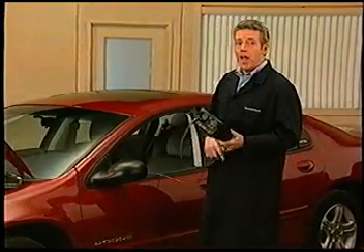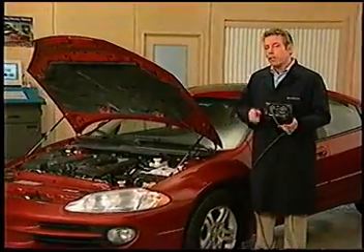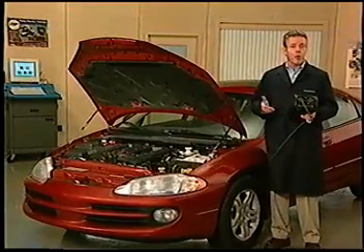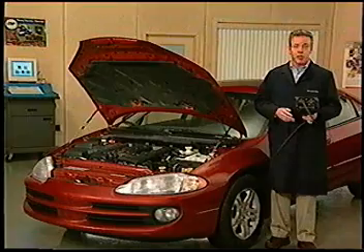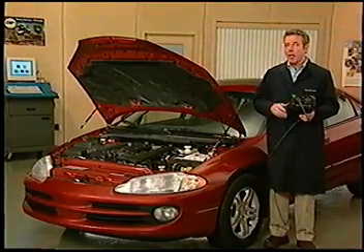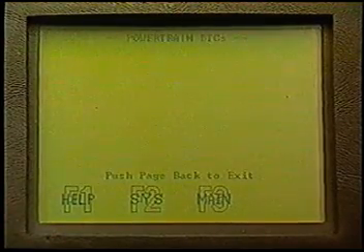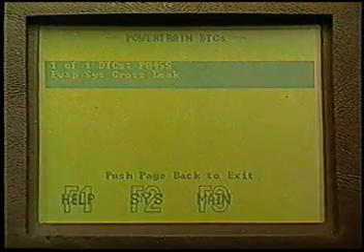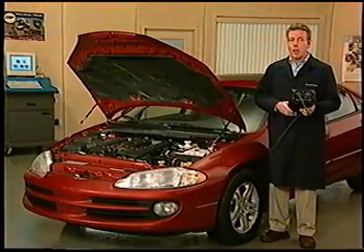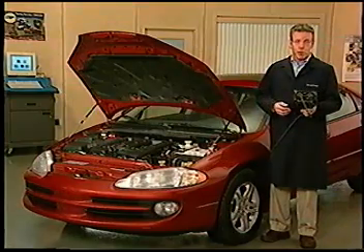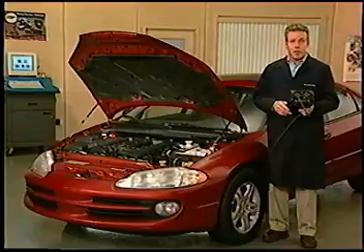Now that you have a better understanding of onboard diagnostics and how it works, let's take a look at some service concerns that you may come across during your diagnosis. We'll begin by going over a couple of diagnostic capabilities the generic scan tool has that you may not be aware of. First, like the DRB3 in standalone mode, you can use the generic scan tool mode to retrieve fault information. If you'll recall from the December 2000 program, this can be very useful if you were to get a no response message from the PCM while using the DRB3.